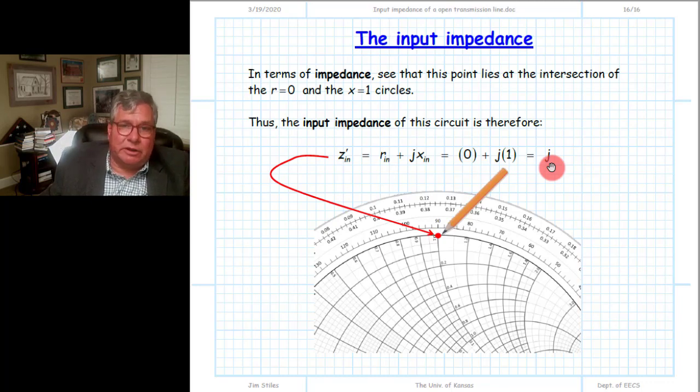Now, what we want to do is really understand what the Smith chart is, what we are doing, why we are doing those rotations, why they are circular arcs, and in which direction we rotate. All this makes perfect sense if we understand the Smith chart and our mappings from the complex impedance plane onto the complex gamma plane.